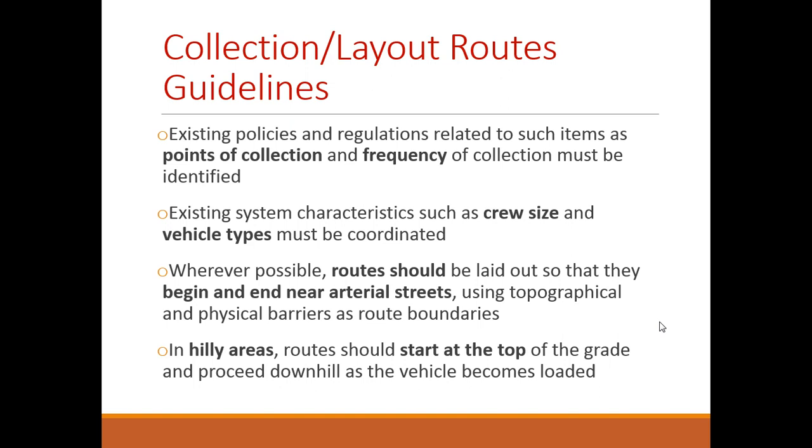We also want to look at existing system characteristics, such as your crew size. Is your crew size sufficient to meet the needs of your collection route? What about the vehicle types? Are your vehicle types sufficient as well? We looked at a few vehicles before. Do you need a standard size vehicle? You want to consider your waste generation rate. Do you need to provide a collection vehicle of a larger size? All of these things you would want to consider.